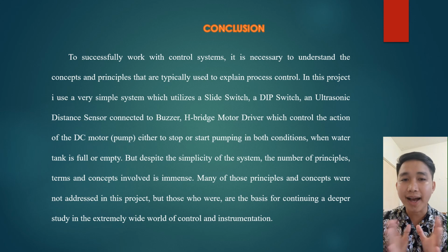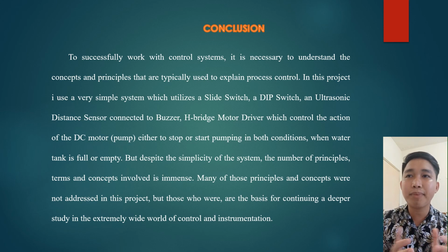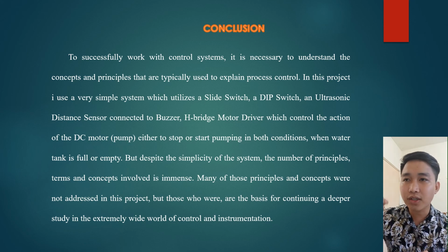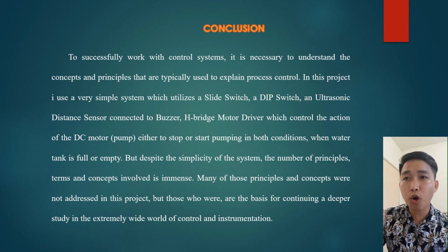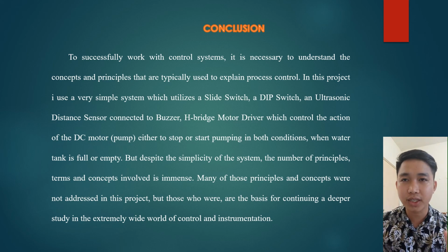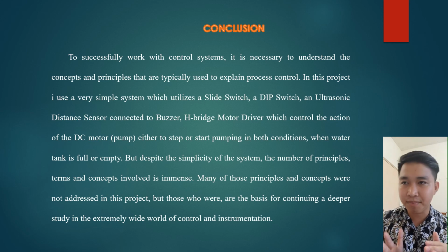In this project, I use a very simple system which utilizes a slide switch, dip switch, and ultrasonic distance sensor which is connected to the buzzer, and an H-bridge motor driver which controls the action of the DC motor either to stop or start pumping in both conditions when the water tank is full or empty.